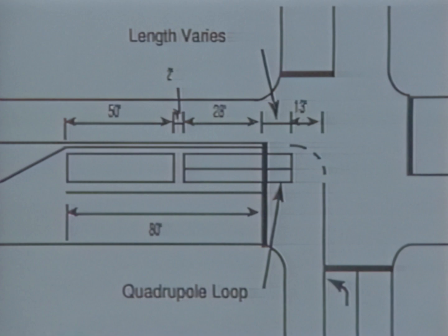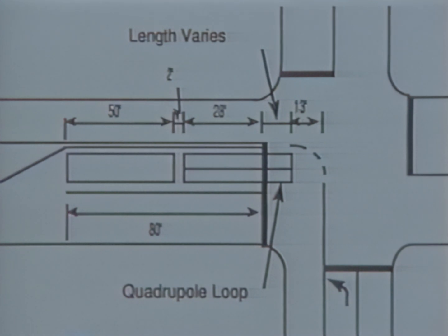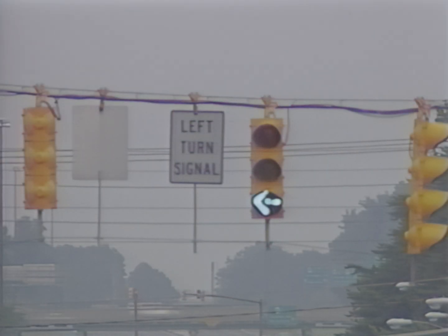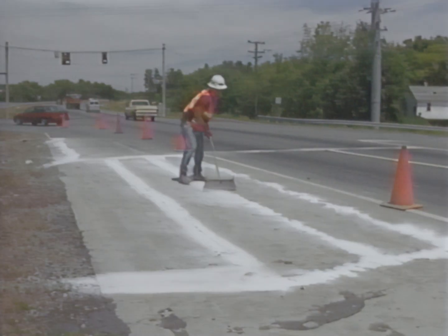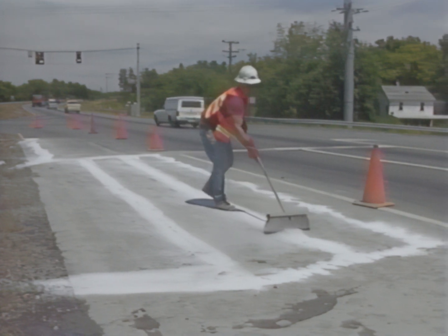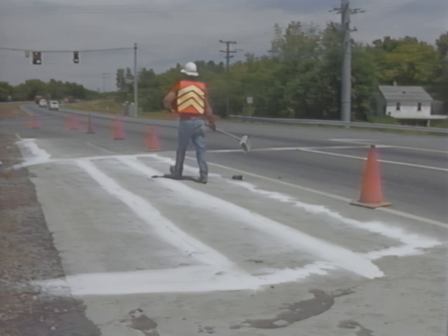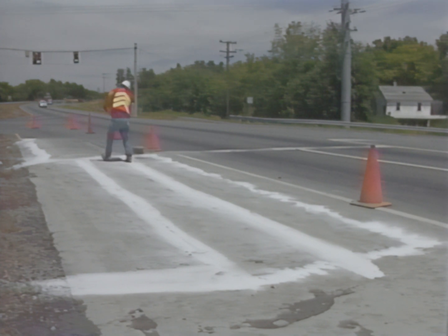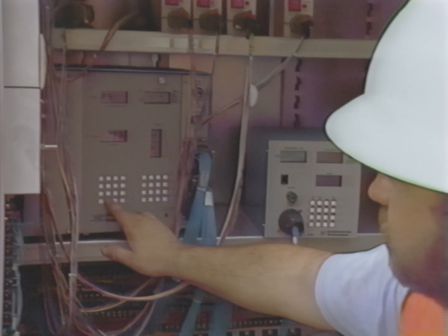The next loop detector design alternative is left-turn lane detection. Positively affecting the capacity of an intersection, left-turn lane detection reduces unnecessary green time and sometimes the need for left-turn arrow indications. In our left-turn lane example, a 6-by-30-foot presence detector loop is used and the controller passage time is set at 2 seconds. If shorter loops are used, compensate by adding more passage time on the controller.